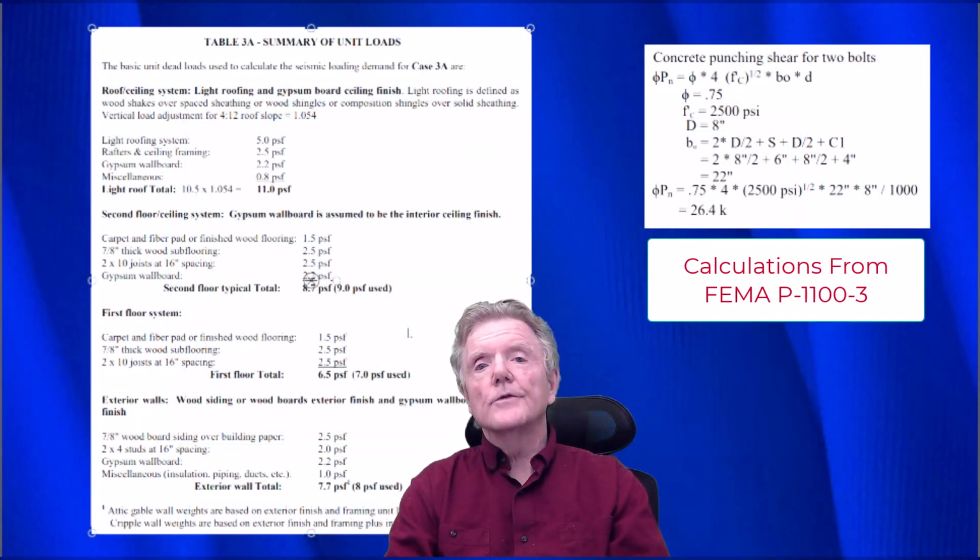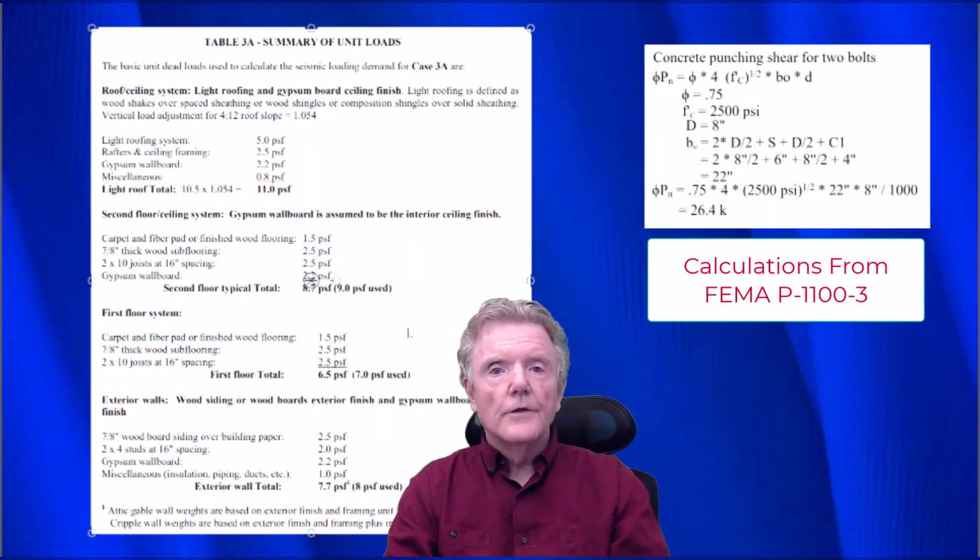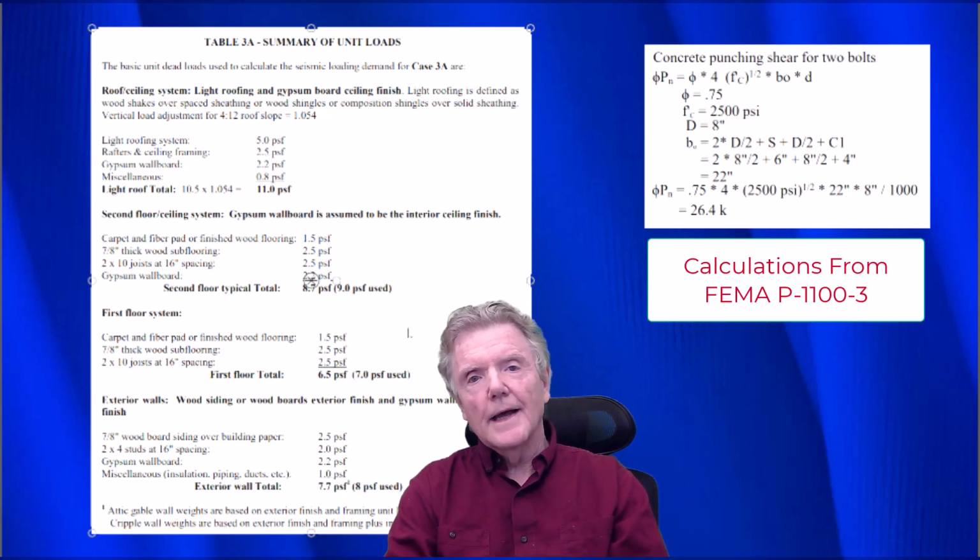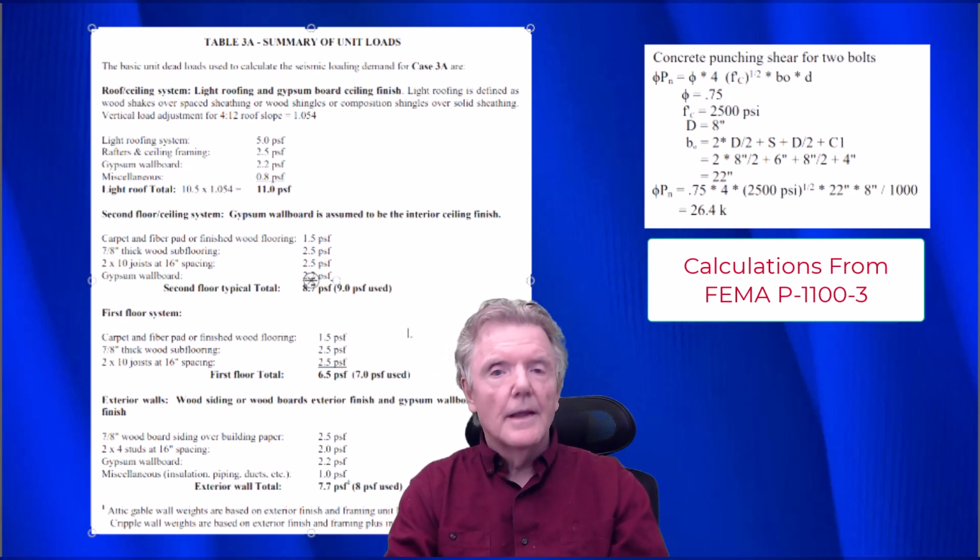As you saw, houses with stucco siding do really well. The cripple walls do not collapse. And I was also able to show you that according to engineering calculations, which are part of the old building code table that I showed you, there's a very rational reason why that is. So, a house like that with cripple walls and covered with stucco, a single story, we were looking at a single story here, are very earthquake resistant as is. And frankly, if I was a little short on money, I wouldn't bother to retrofit it. I mean, because empirically, based on evidence, it probably won't collapse.